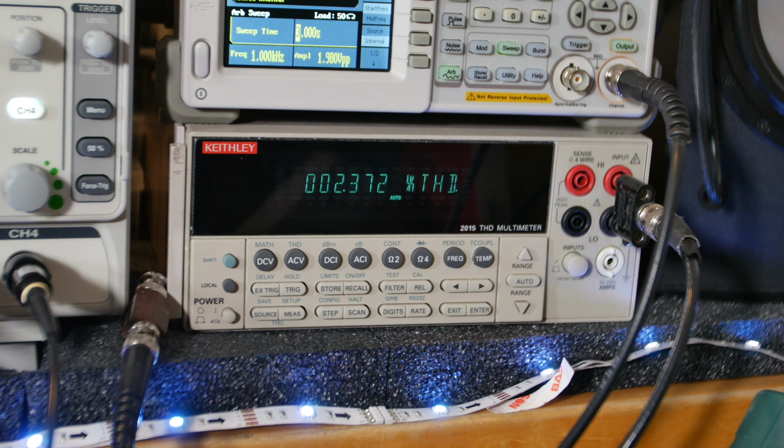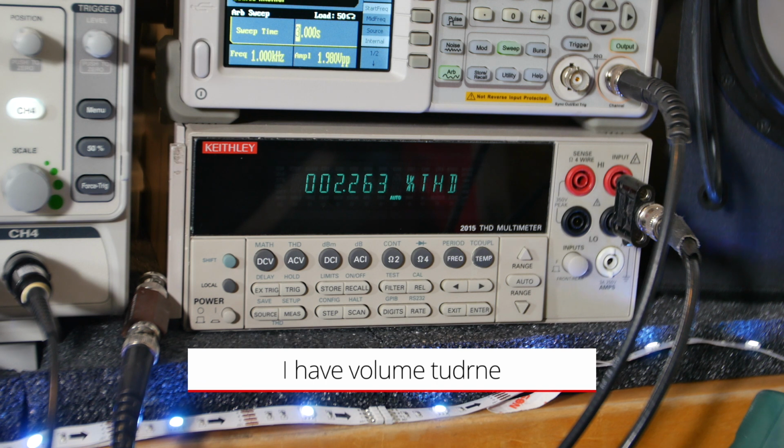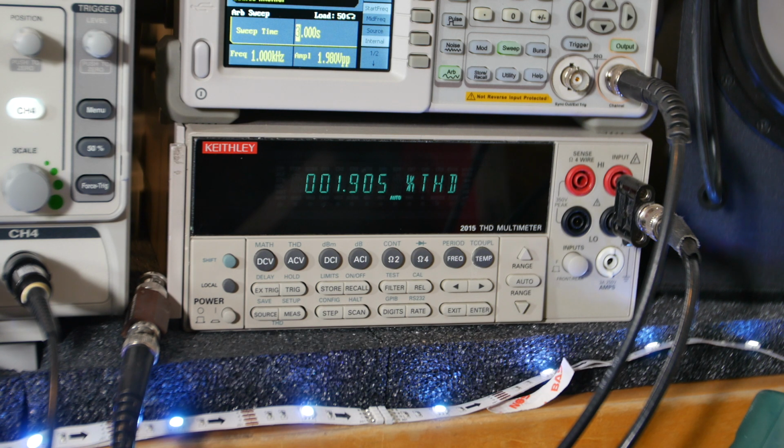That's because the signal is so low. The 1 kilohertz signal is so low that the noise matters: I think the signal is down around -30 dB, and the noise is down around -40.